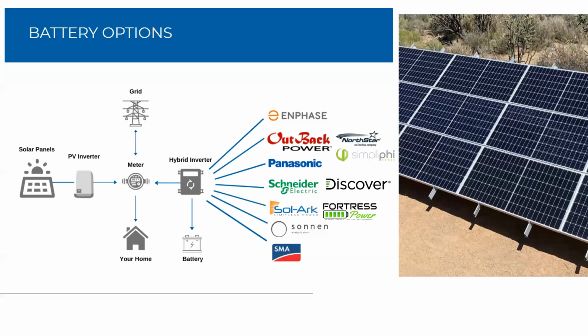If you just Google home energy monitor, when you install solar for someone, throw on an energy monitor so that you can get a good understanding of what the homeowner is actually using when you want to add a battery, because it's really hard to know. Like, I don't know, I just live in my house. It's a 1,600 square foot house and I live my life like normal. I don't necessarily know what that equates to in terms of kilowatt hours. So having a monitor helps, and reviewing loads one by one, honestly, with the homeowner.